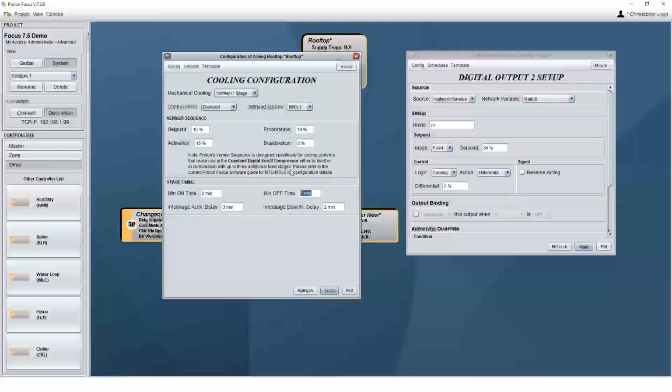There's nothing else out there operating in this manner until you just get straight into a VFD compressor. One of the problems with the digital scroll is that it is allowed to operate at such a low capacity, we cannot get adequate oil return to the compressor.